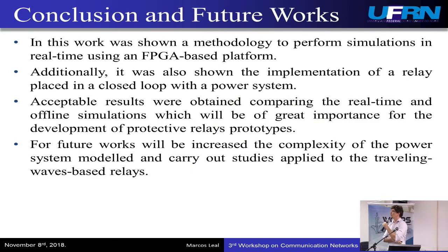In this work, a methodology to perform real-time simulation was shown. Also shown was an implementation of a relay placed in a closed loop with the power system. This work is of great importance for the development of protective relays, prototypes, for instance. For future work, we will increase the complexity of the power system and carry out studies applied to traveling wave-based relays.